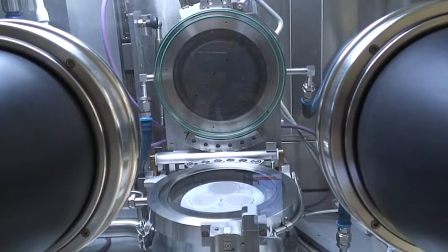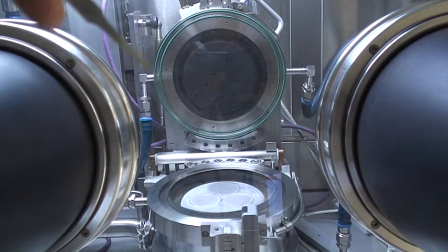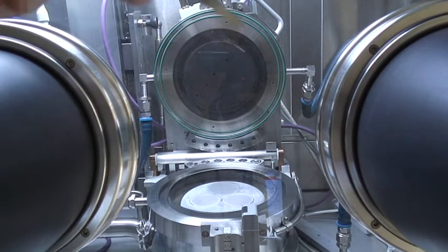This is the reactor we use for the MOVPE growth. The top part here, where I'm using my tweezers to point, is the shower head. It's got a lot of small holes in it which inject the gas from the metal organic sources and from the ammonia bottle into the reactor chamber. Half the holes introduce the ammonia gas we use, and half introduce the metal organics which contain gallium, aluminium and indium. We also have dopants which come in through the same holes.